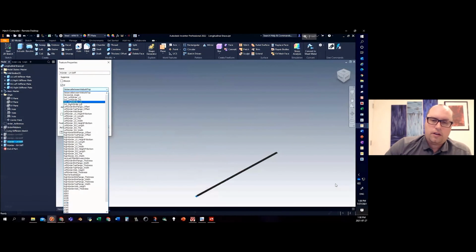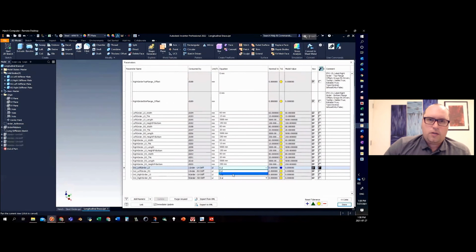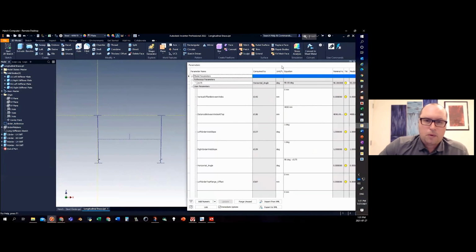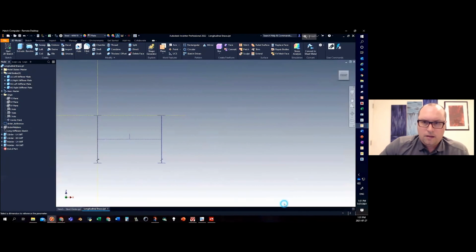And as well, the iLogic rules that you would create in the Inventor models, or the ability to toggle things on and off, do translate into InfraWorks. There's some limitations that you can't use all the iLogic capabilities, but for the most part, you get everything you need to.